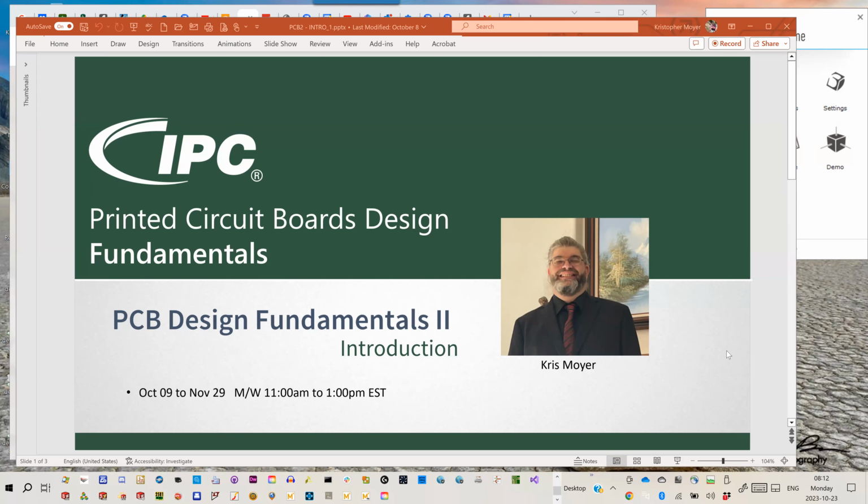So deleting versus just leaving them there is a personal choice. I will also show you how you can use rooms for other features in the tool other than just placement. They actually allow you to create area rules. We are going to use an example of an area rule when we get to our BGA, where we're going to allow narrower trace widths and or smaller clearances only in the area of our BGA. So there are other benefits to leaving the room in there, even if you have it invisible. So I personally leave it there.